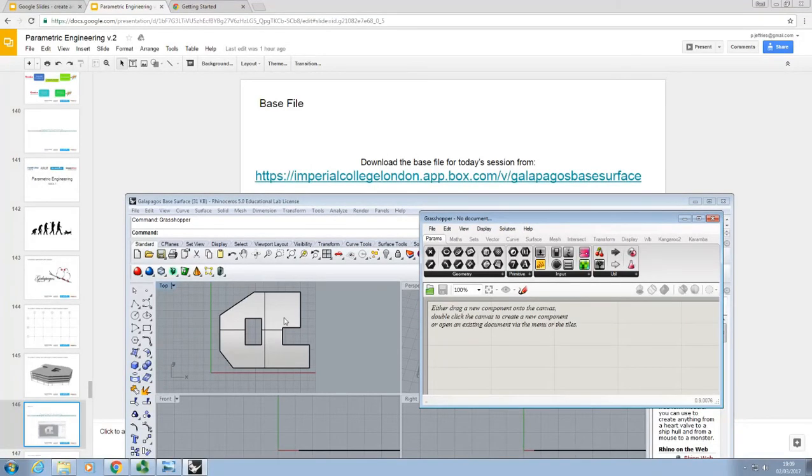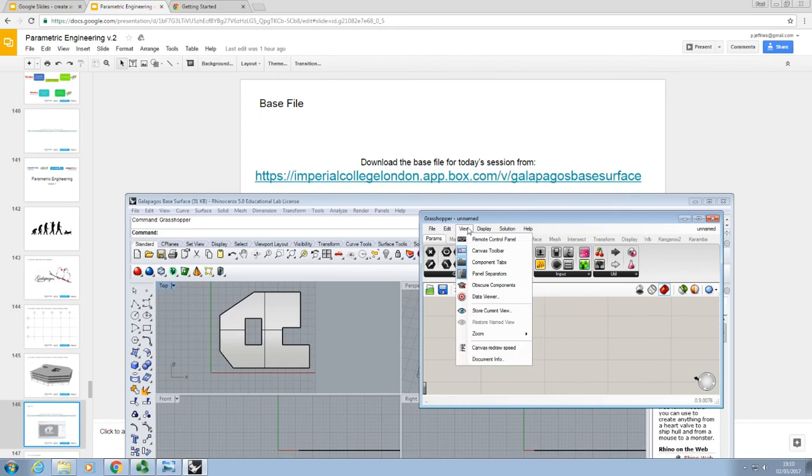So this might be the kind of arrangement that you've got from an architect. He might send you a CAD file or something like that with this arrangement in. It's not too uncommon that you would receive something like this and then have to work from it. So first of all, we'll bring that surface in using the surface parameter component under Params, Geometry. So as we've done many times before now, we'll drop one of those down. We will go to display and put draw icons on.